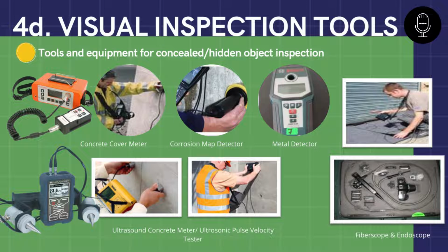Second, corrosion map detector. This tool is used to inspect a material where oxidation or erosion has reduced its thickness. Since an ultrasonic path is directly reduced on a corroded part, a conventional UT beam can report one specific thickness at a time, while a phase array scan can produce an array of thicknesses.